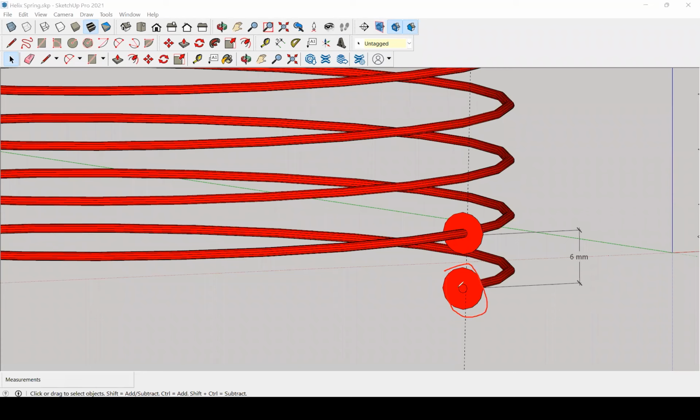We start here, and in order for you to make one complete revolution would be right here, right? Let me use a different color so that you guys can see. So you start here. This is where you start. And if you wanted to make one rotation, one rotation will end you back up here, and that would be our pitch, right? One complete rotation will end right back up here, and they always line back up directly above each other, right? So that is how we can define the pitch there.